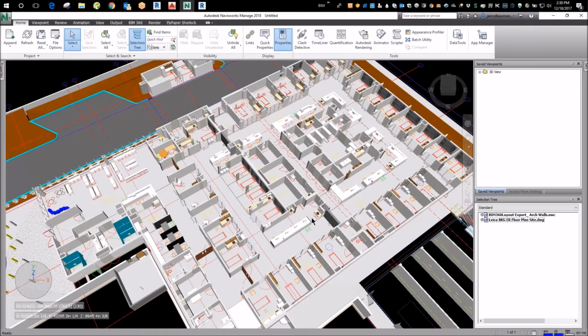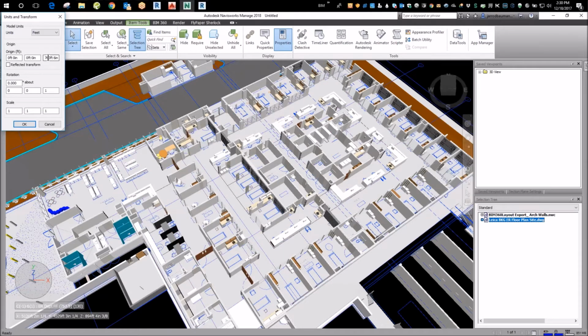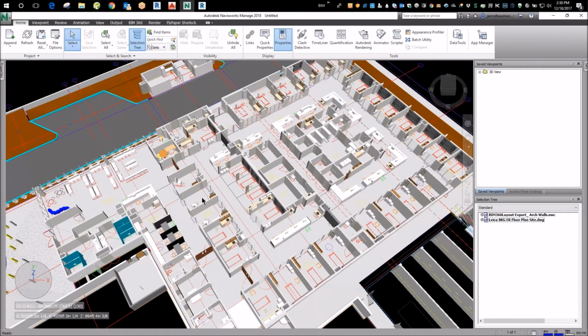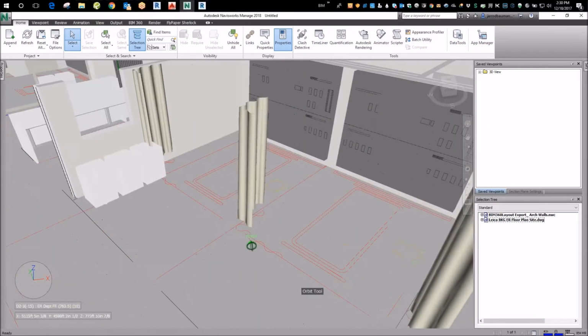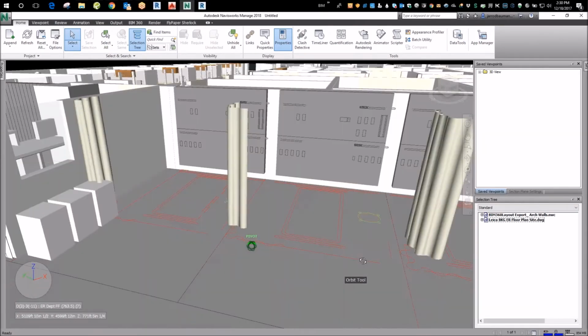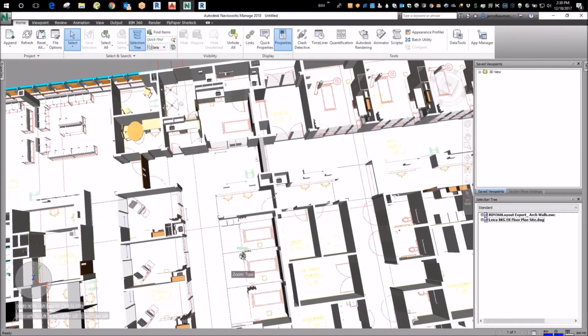Now what happens after you change that? If you want to see it again, make sure when he puts it in, Blair, that it's 763 FT space 6 IN. I wish you could type 763.5 and have it be smart like Revit. Revit will automatically convert. Navisworks does not. So now, if you did it right, you should have a CAD file right at the floor, the slab, right? I still had 1 or 2 elements that didn't come up for whatever reason.